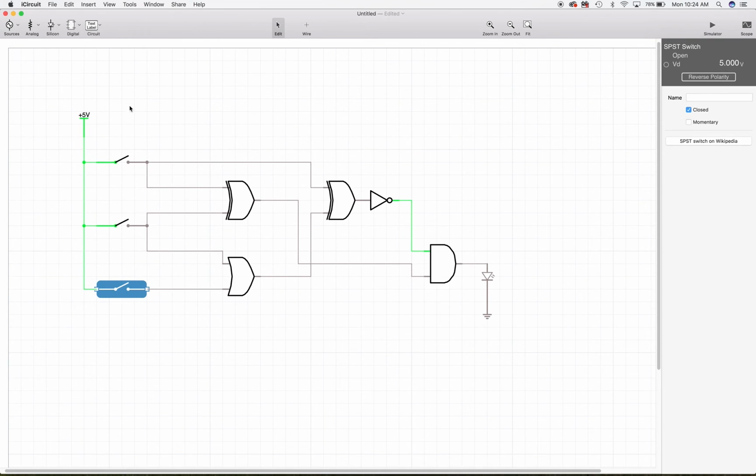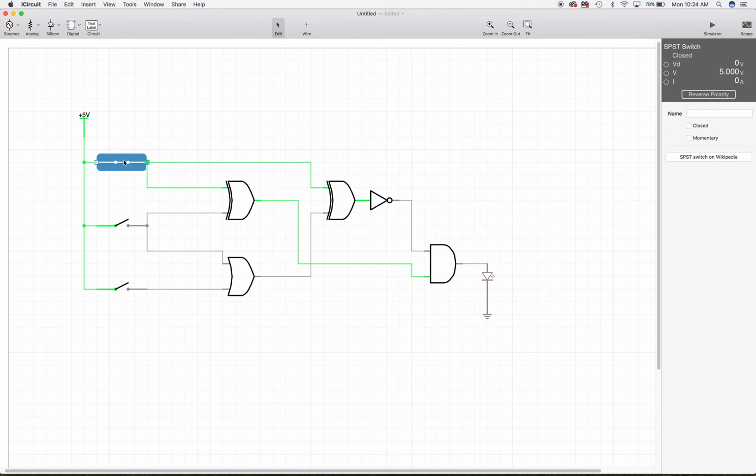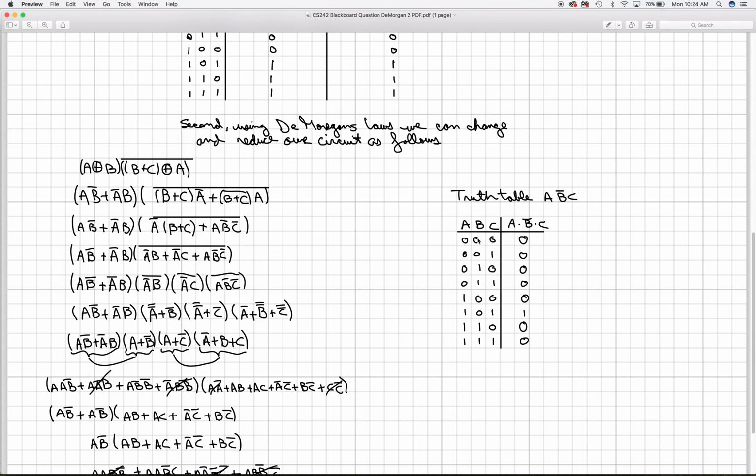So this is like really the same thing as binary 0. This is binary 1, still off. Binary 2, still off. Binary 3, still off. Binary 4, still off. Now, binary 5, right, that's on, off, on, so that's the option that it works. And then binary 6, off. Binary 7, off. So as you can see over here, for binary 0, 1, 2, 3, 4, 6, and 7, it's off. And only when you have binary 1, 2, 4, that's 5, is when the circuit is actually on.